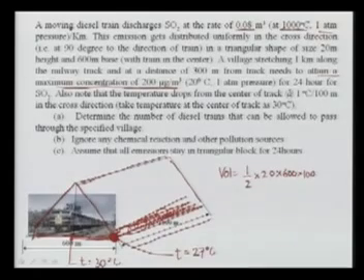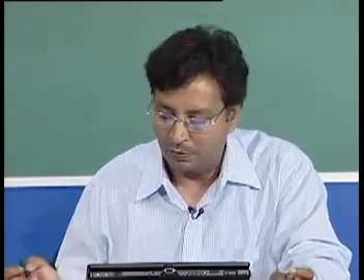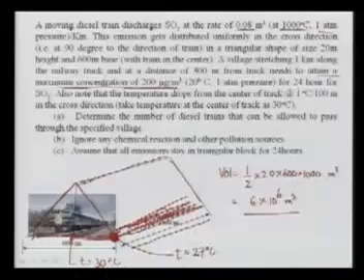So, this is the area in meter cube in which all the pollutants will be dispersed. Let us find out how much this comes out to be, and I have a calculator here. I will try to calculate this for you quickly. 20 into 600 into 1000, and divide by 2, is something like 6 into 10 to the power 6 meter cube. Okay, so we'll remember this number, that the air pollutants discharging from the diesel train will be completely mixed in this area.